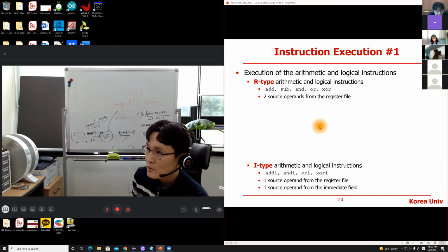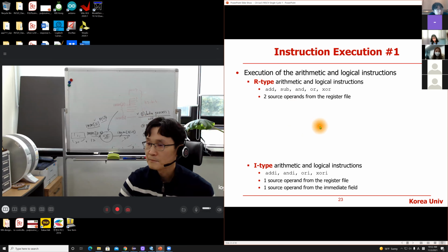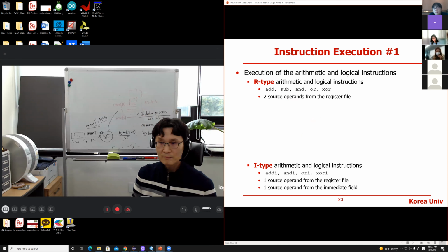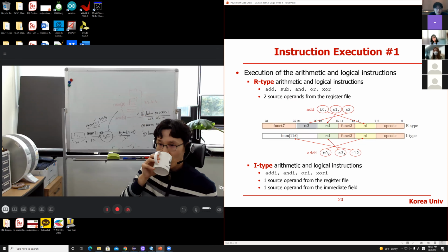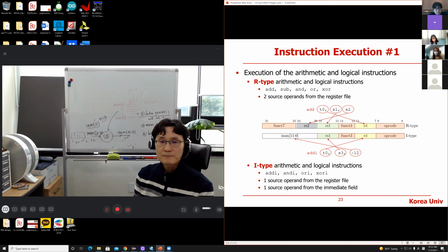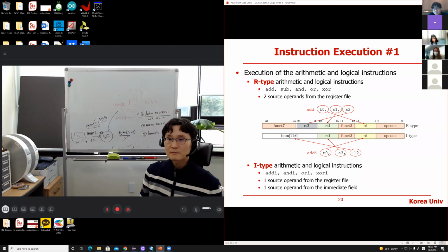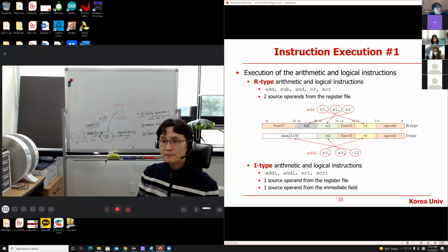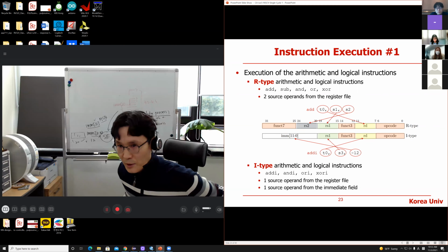Sujin, can you please? Can you hear me? Instruction execution 1. Execution of the arithmetic and logical instruction. R-type arithmetic and logical instruction: two source operands from the register file. I-type arithmetic and logical instruction: one source operand from the register file, one source operand from the immediate field. Okay, thanks.